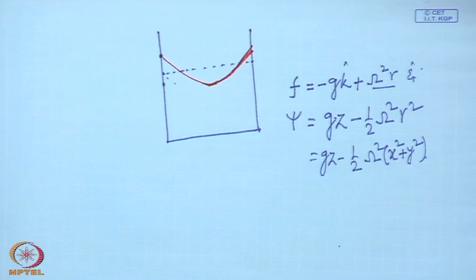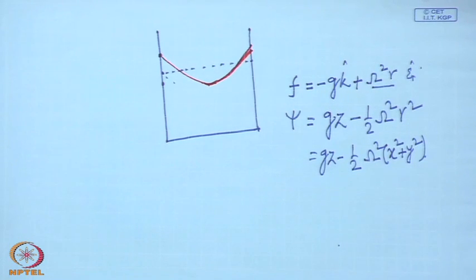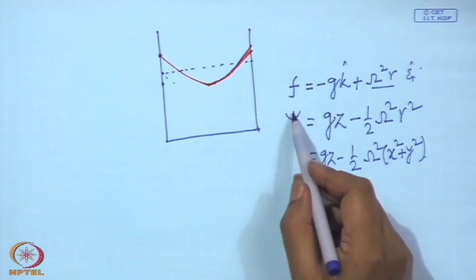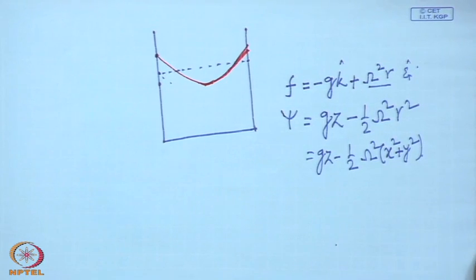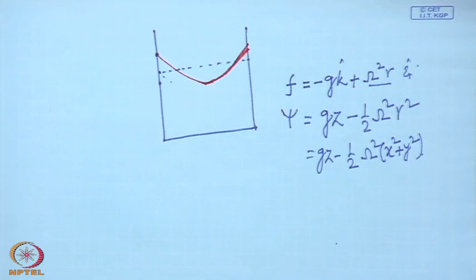Without proceeding further, we can say what the level surfaces are from here, and the level surfaces for pressure and density are the same, which shows it is a paraboloid of revolution with vertical axis shifted vertically.